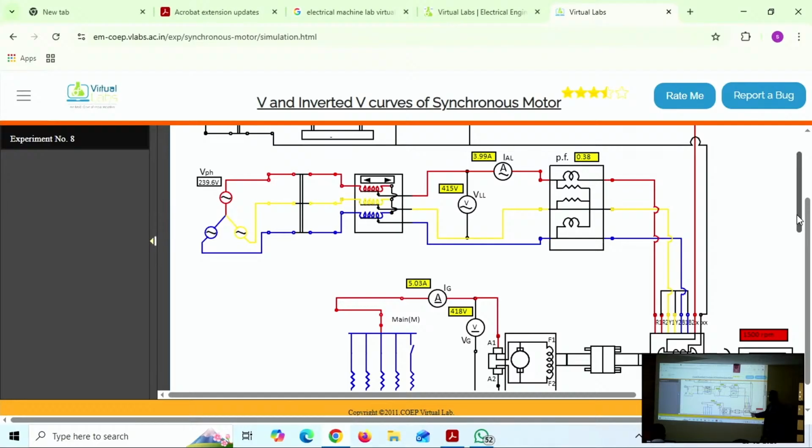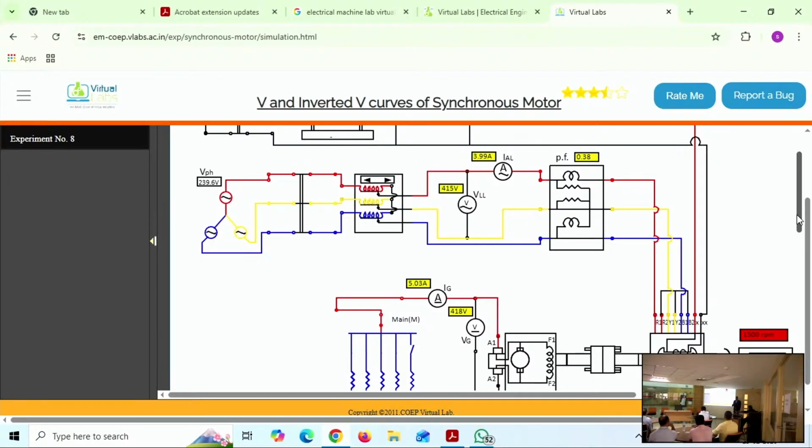Okay. Again, is the synchronous motor self-starting? No. The synchronous motor is not self-starting, because first the rotating magnetic field exists that rotates with a certain speed. Physically, the rotor has to move along with that speed. No, it cannot happen on its own. We need certain arrangements. Depending on the type, usually at laboratory scale, we have induction start synchronous motors, just by use of damper windings. So there are certain arrangements on the rotor side. Earlier in theory classes, professors discussed that, right? A synchronous motor cannot start on its own unless some external means is provided, right?